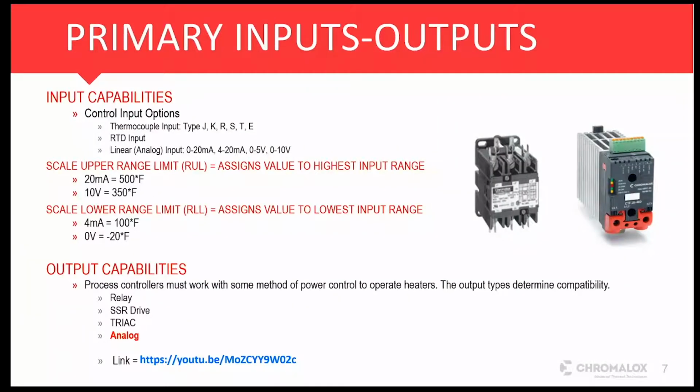From there, it comes to the more standard stuff, like what's your input type, how to set those input types, and we're going to walk through that in a little bit. But there's a couple things that get overlooked that you may not be familiar with or have enough exposure to. And that would be maybe along the lines of an analog signal. It's very, very important in all of these controllers to scale them and how to scale them.